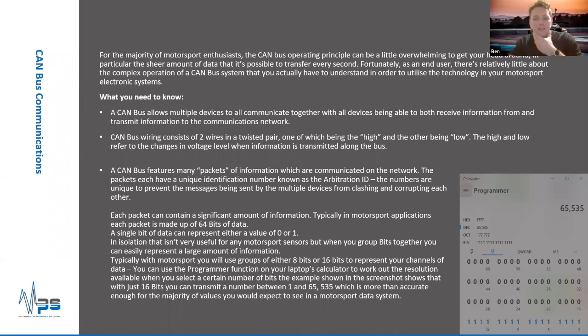And there's a huge amount of available identification numbers you could choose. And then once you have a CAN packet, there's a large amount of possibilities of where you could hide your data within this CAN packet. So if I'm trying to make my ECU send me throttle position, for example, there's an almost infinite amount of possibilities it could be hiding on a CAN bus system.